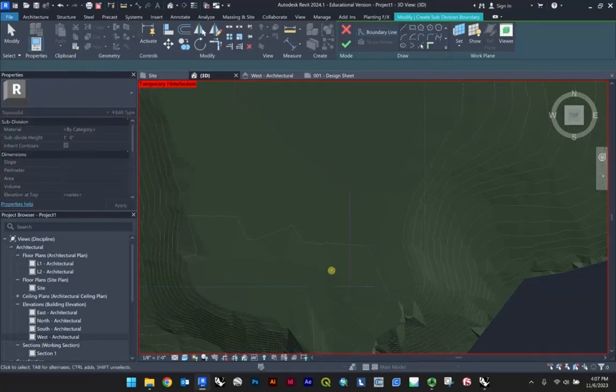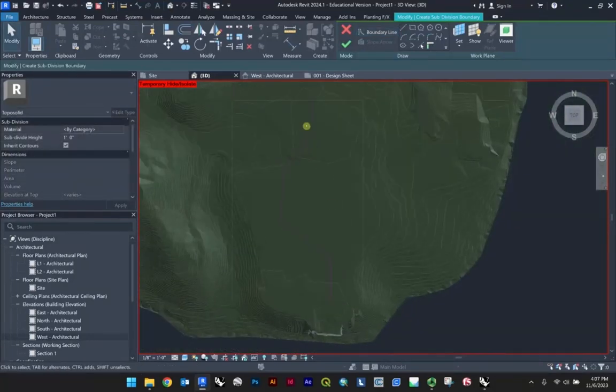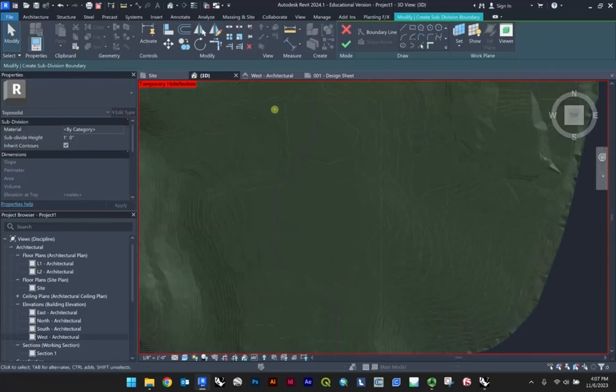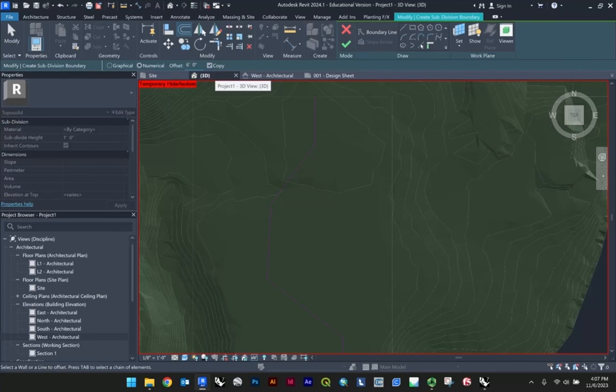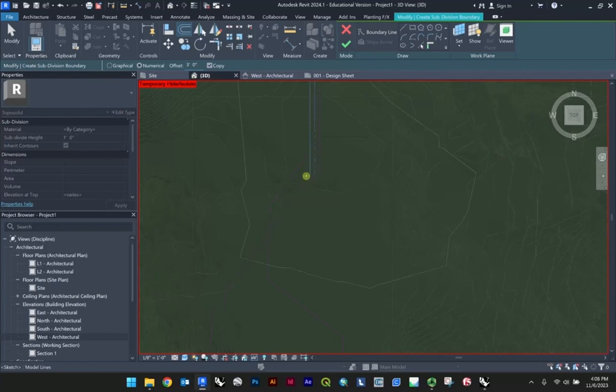And let me close out of it there, just so I can show some other commands. So this is, let's just say, my center line for this. What you could do here is start to offset your work. So you could do offset, and you'll see the offset here is 1 foot. Now, if we want to make, say, a 3-foot path, or a 6-foot path, we could do 3 feet here. And just start to offset this on either side.